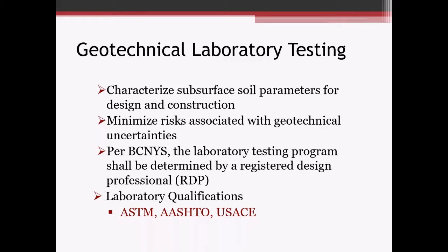One of the main sources of error that sometimes occurs can be due to sample disturbance during the collection and testing. So it's important that proper procedures be followed from sample collection to completion of the lab testing. And per the building code in New York State, the laboratory testing program is determined by the registered design professional, which is typically the geotechnical engineer of record for the project.